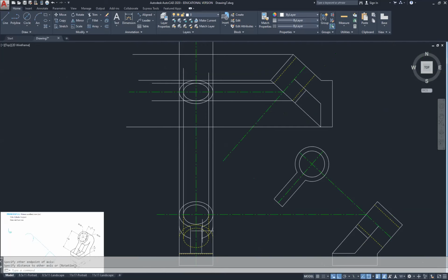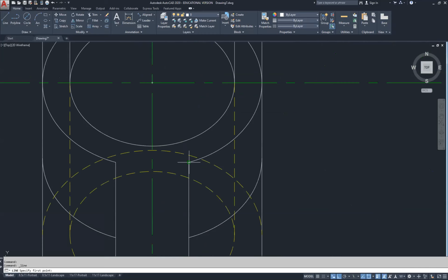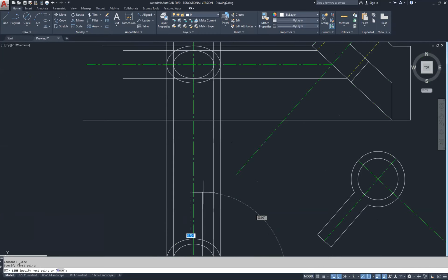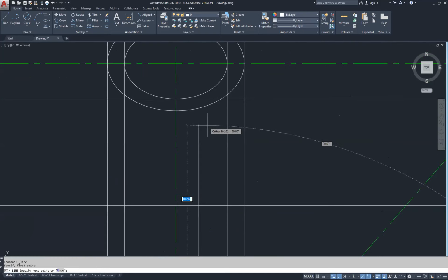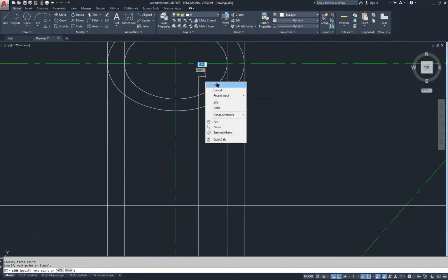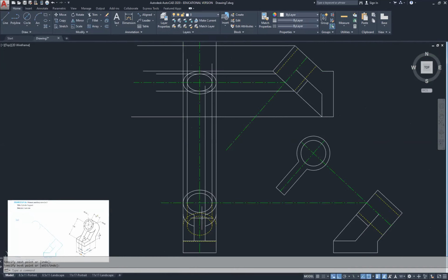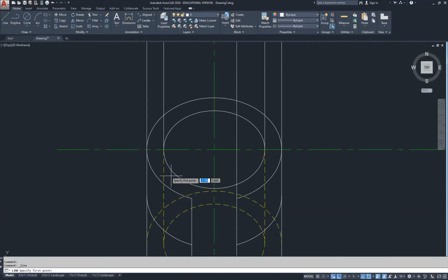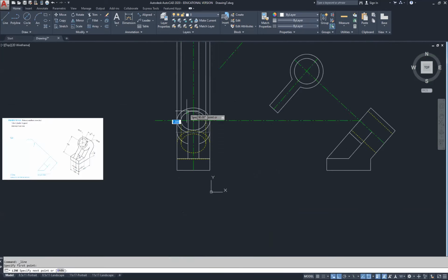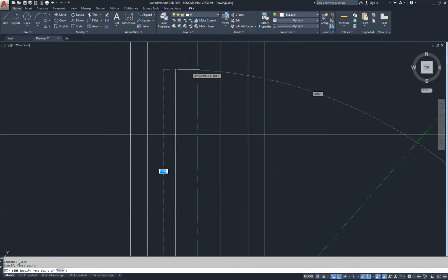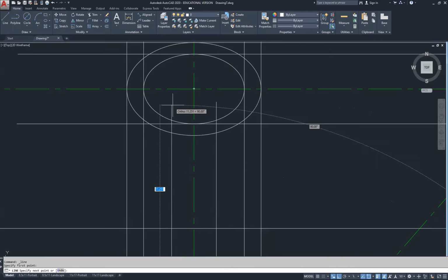Now I need that rib. So I'm going to project that across. Be careful where you snap. I'm just going to go ahead and go a little bit past. Make sure you zoom in and zoom out when you're doing this. Check that rib here. And select somewhere around here where that ellipse stops is going to be here at this intersection to this intersection.